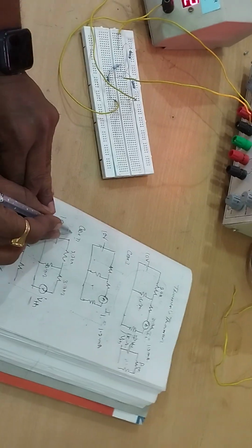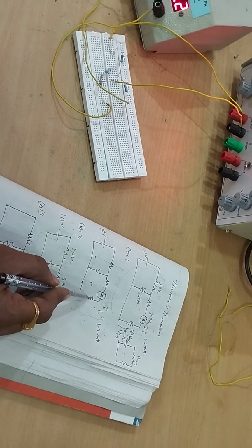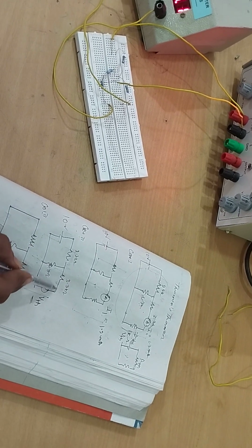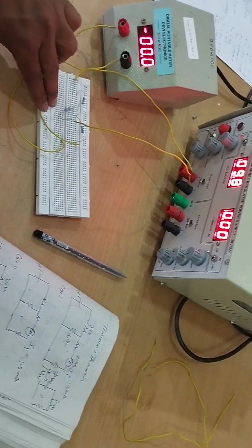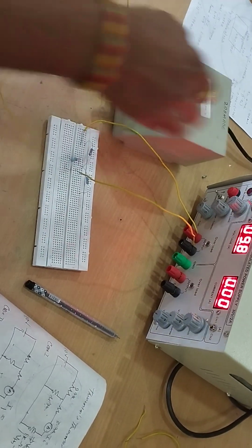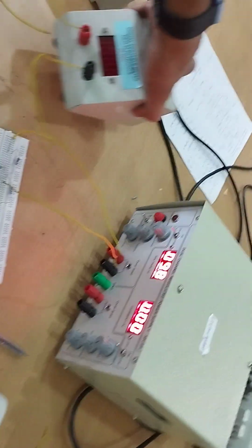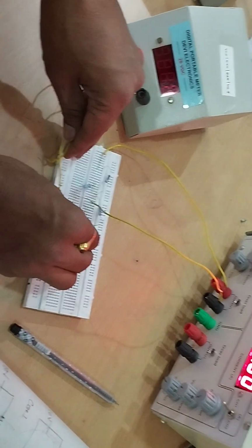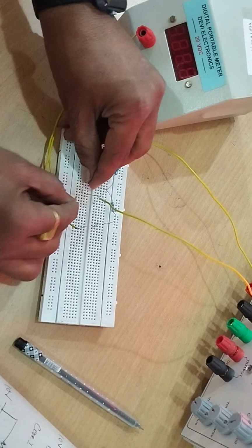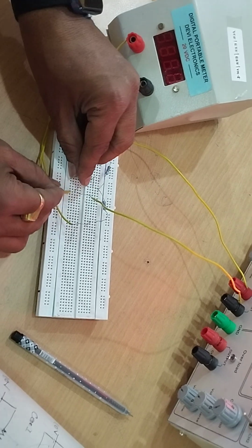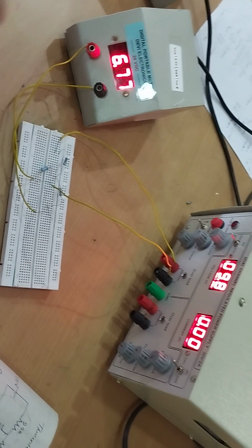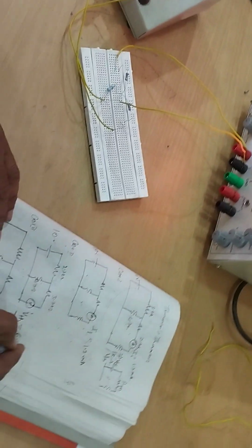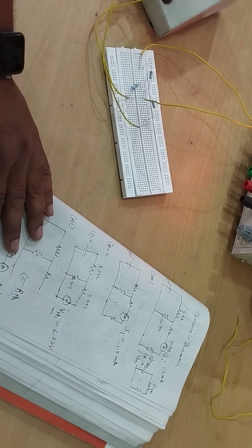Let us come to case 2. Remove the load resistor and the ammeter, and replace with a voltmeter. So I'll remove the load resistor. This load resistor is removed. Remove the ammeter and take the voltmeter. This is the voltmeter. Connect the voltmeter across the load end and measure VOC, the open circuit voltage, in the same section. How much is it? 6.77. This is 6.77 volts, right?